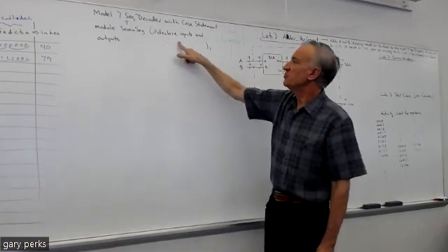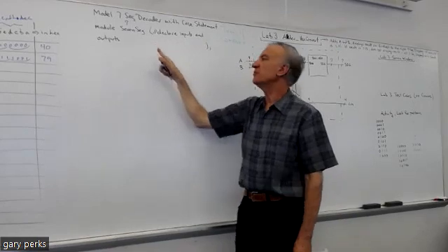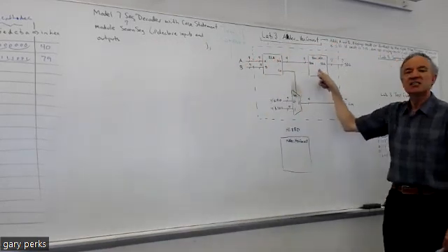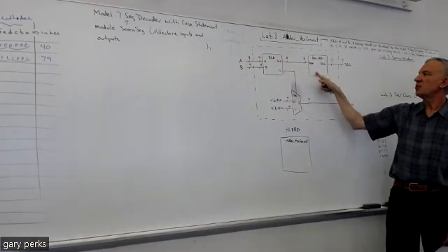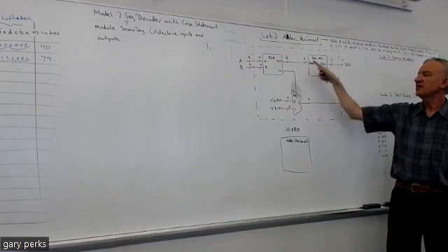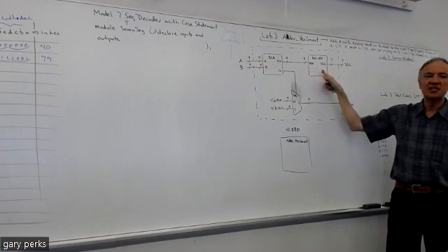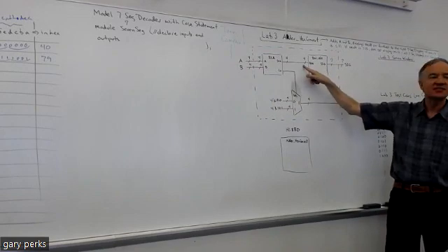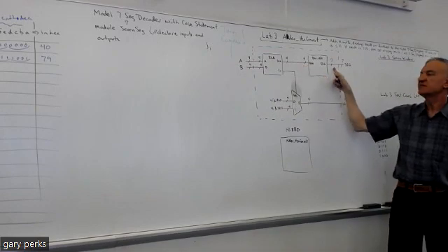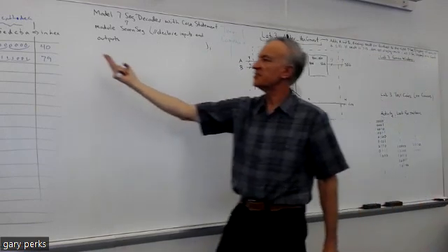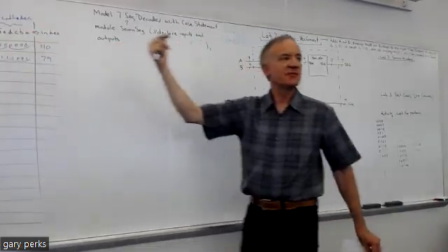So you would declare your inputs and outputs just like you've done before. So here again, this is our module. This is like our high level, if you will, for the decoder. There's only one main input, and only one main output. 4 bits, 7 bits, right? You need 7 bits because there are 7 segments.